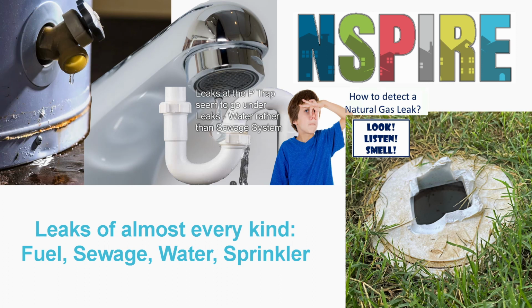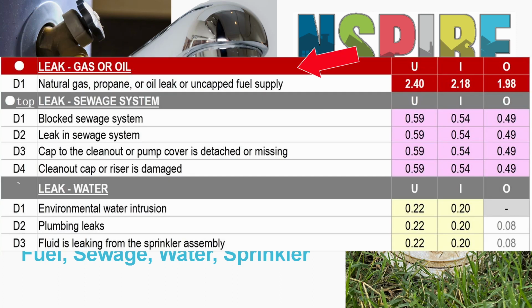Let's take a look at all the different types of leaks that are spelled out as leaks under the new NSPIRE standards. There's one type of leak that falls under the inspectable item leak, gas or oil, and this, of course, is the highest scoring of all leaks. It's a fuel leak. Deficiency 1, natural gas, propane, or oil leak, or uncapped fuel supply. This has a value of 2.4 in a unit, 2.18 inside, 1.98 outside. This, of course, assumes that we're inspecting a total of 25 units. And a fuel leak is obviously the most dangerous type of leak, and it's hopefully rare.